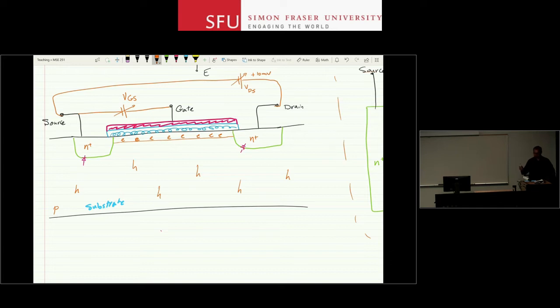And then what happens next? Now, from here to here, from the source end to the drain end, so far you didn't have any contact. So far you had two reverse bias diodes, but all of a sudden now there is a very thin N region that connects these two regions, N plus at the source and N plus at the drain, to each other. It's a very thin region. You still have to push carriers through it. It behaves as a resistor. Now, instead of having two diodes back to back, the diodes are still there.